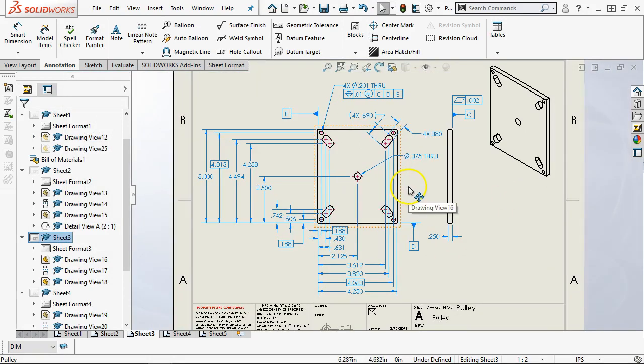All right. So did I make that complicated enough? Positional tolerances are one of those fun things that until it gets tight, the locations start to line up, or we start bringing this tolerance zone down to 5 thousandths or maybe to 1,000th, this becomes pretty critical to the location. So 10 thousandths is a fairly generous tolerance for this to move around, but it keeps us in line with the sketch with the plus or minus 5.